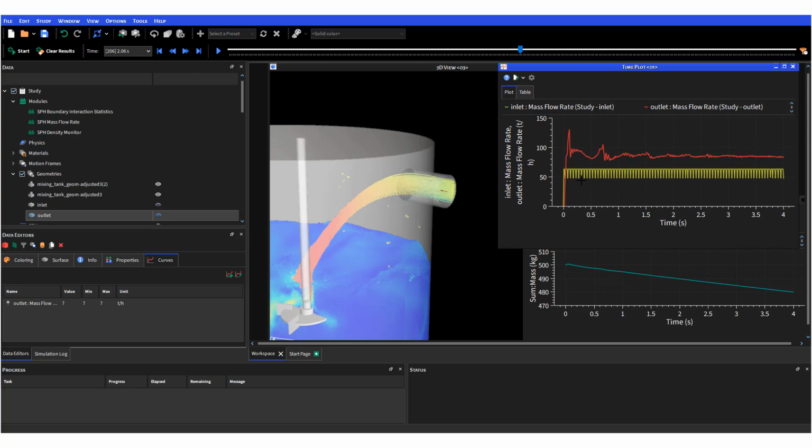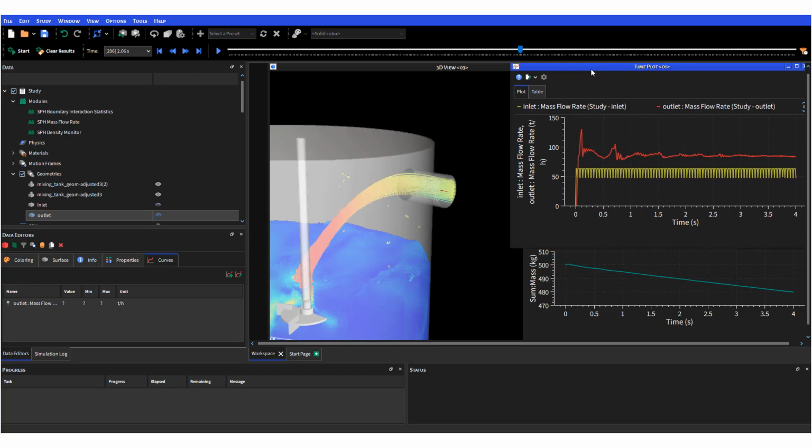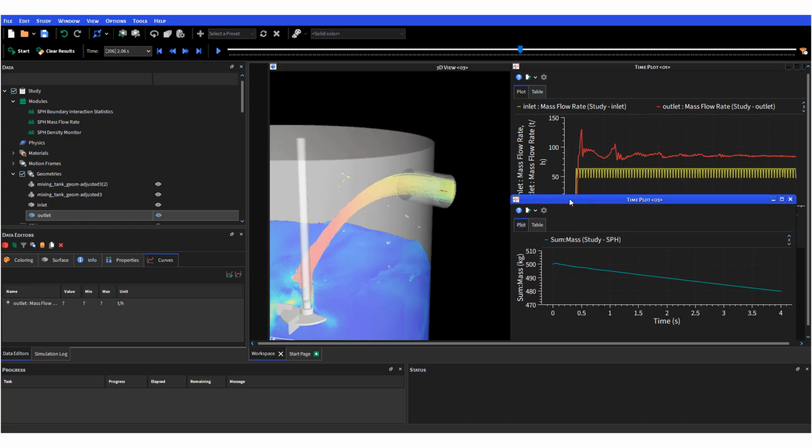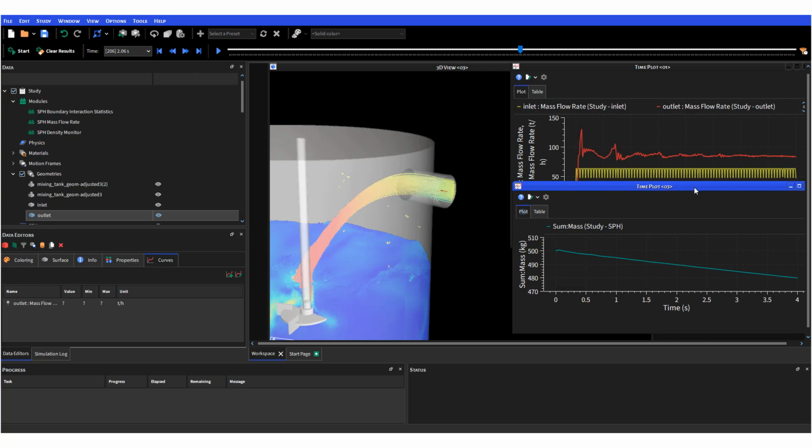You can see that the inlet mass flow, the rate is defined here, is actually lower than the outlet mass flow, which means I'm actually losing mass. So this is not really steady state. I would have to increase the amount of mass flow, or modify the geometry, or play around with the design so that we could reach steady state. But this is not steady state.